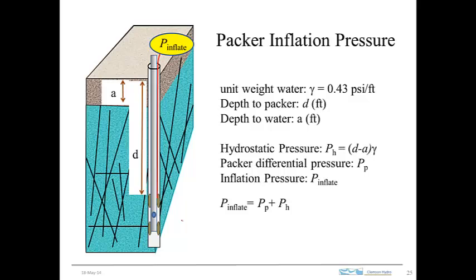So as you put a packer down in the well, it feels the hydrostatic pressure. This contains the packer, and so in order to get the packer to expand, you have to first put enough inflation pressure to just counteract the hydrostatic, and then you have to increase the pressure above hydrostatic to get the packer to expand out.